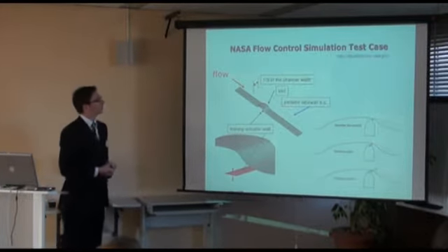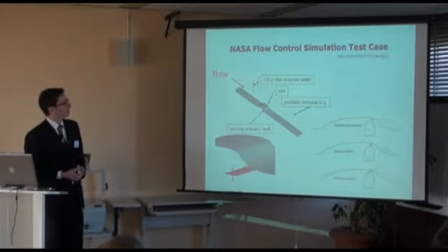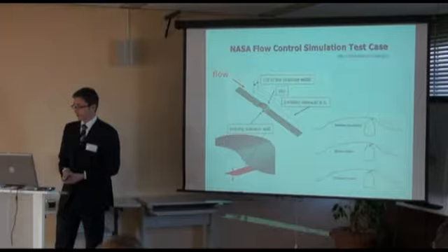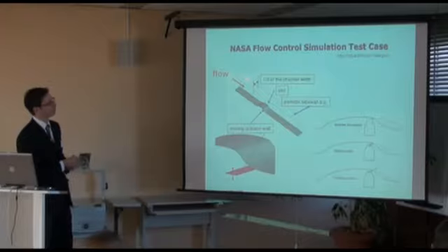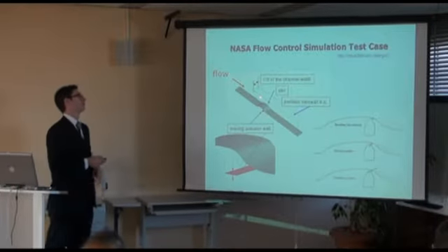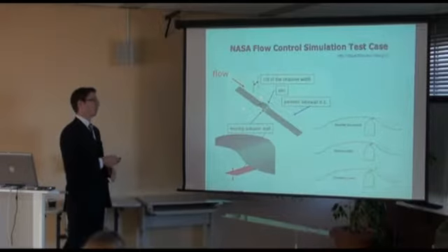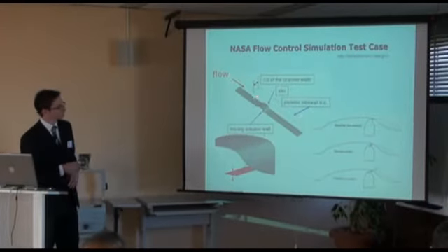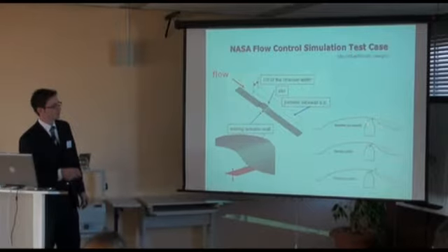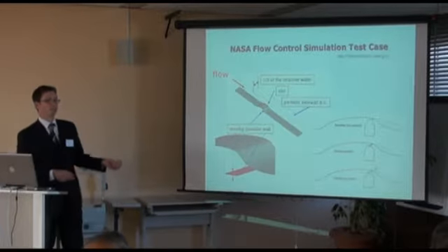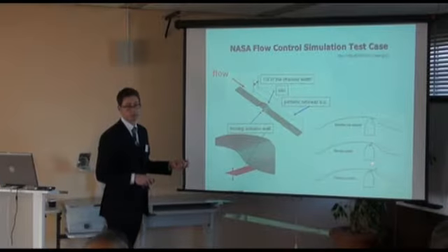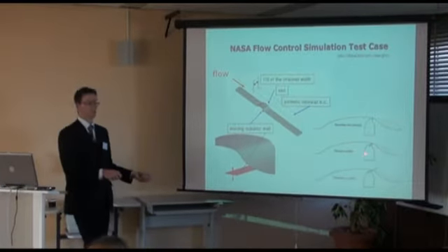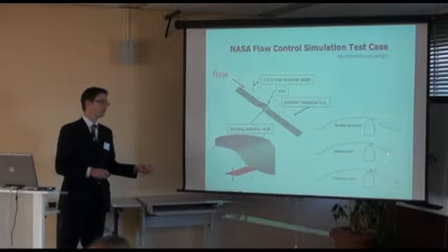And I would like to show you an example from NASA, a simulation example, in fact. Here they've got a very simple straight channel, flat plate, if you want to, with a bump in it. And over this bump there's a separation occurring. If you are doing nothing, you have a separation over this bump here. When you begin to suck away the separation bubble, you of course will have a very small separation, because it is simply sucked away with all this low momentum fluid.